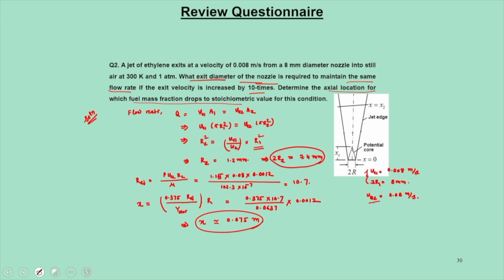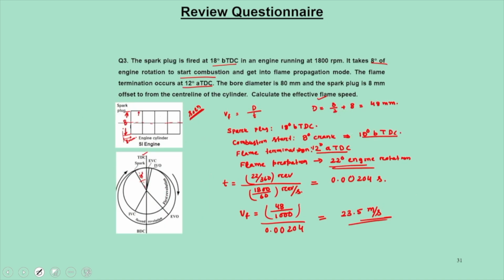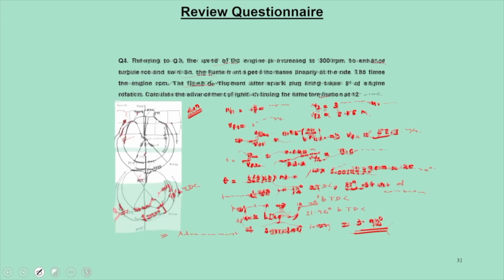This alters the Reynolds number, and as the Reynolds number alters, the jet characteristics change. We look at a similar problem in compression ignition engines to find the flame speed, and this expression shows how the flame speed is calculated in a diffusion flame in a combustion environment.